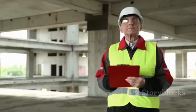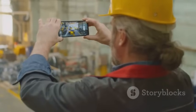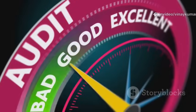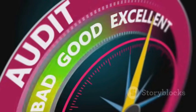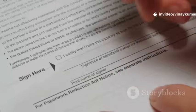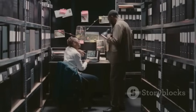They are hunting for gaps between what the PSM standard requires, what the company's own procedures say, and what is actually happening in practice. The result of the audit is a formal report of the findings. This report identifies any deficiencies or areas for improvement in the PSM program. The facility must then promptly determine and document an appropriate response to each of these findings and certify that the deficiencies have been corrected. The two most recent compliance audit reports must be kept on file.